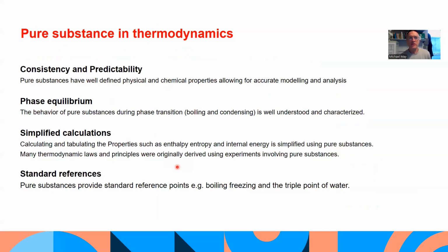Now, the reason why we're interested in pure substances in thermodynamics is because they make up the working fluids in a thermodynamic system. And the simple example there would be in the power plant. We describe the power plant as a heat engine, and the thermodynamic working fluid in a heat engine is pure water. And the reason why water is used is, first of all, it's readily available. It's also got good thermodynamic properties. It also is non-reactive and non-toxic, so it's not going to explode on us.